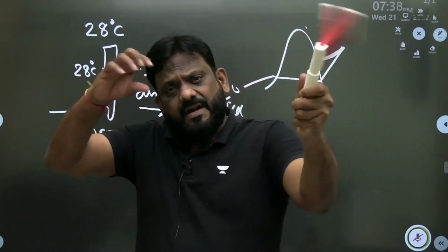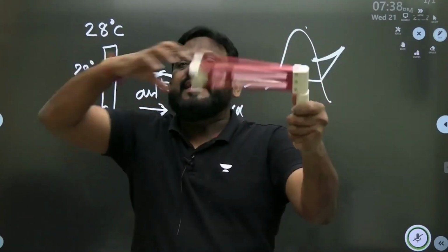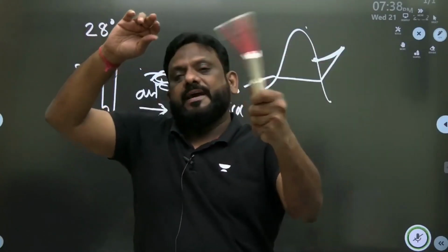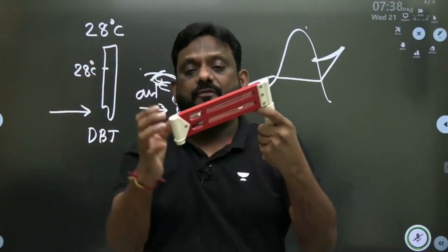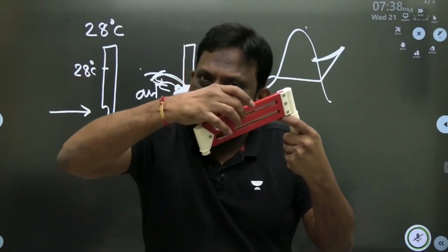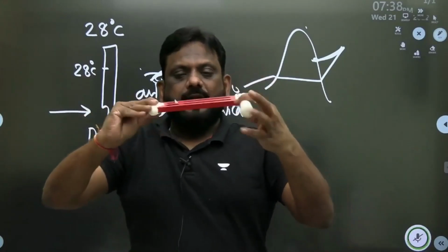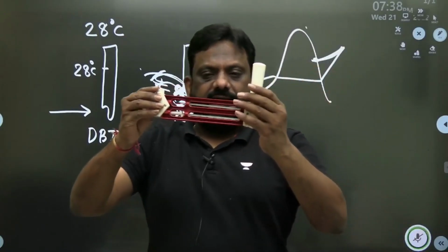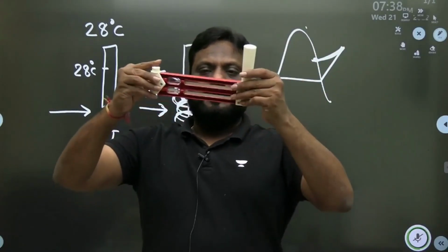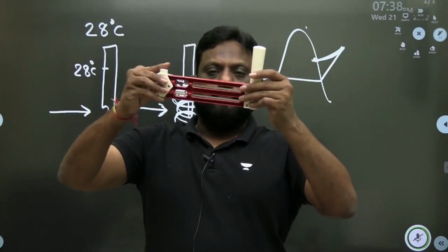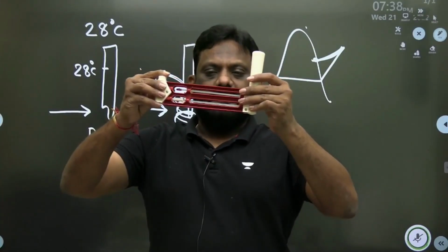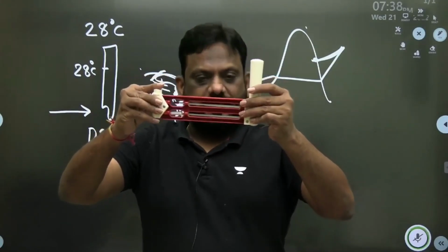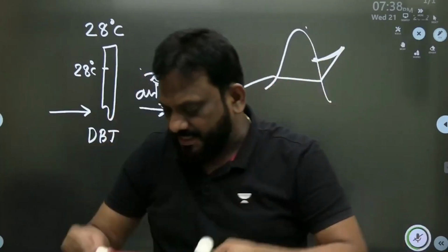The wick which is covered with water, completely saturated with water, the air absorbs that moisture, and thereby in the process of evaporation, observe here, the temperature of this wet cloth, the thermometer covered with wet cloth, will come down. So the AC is running here. Now the dry bulb temperature is about 24 and the wet bulb is around 19 degrees centigrade. You cannot say it, it is 19 degrees centigrade.